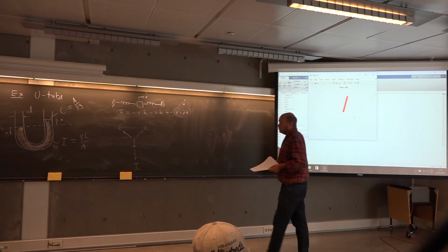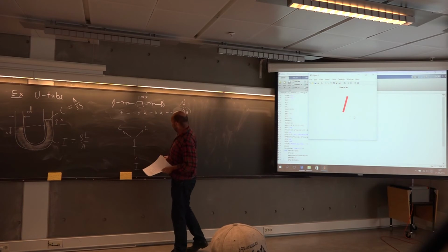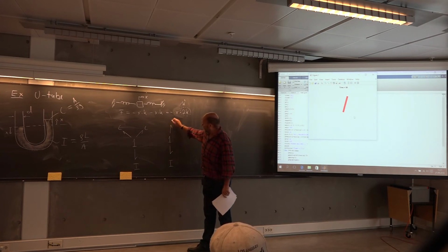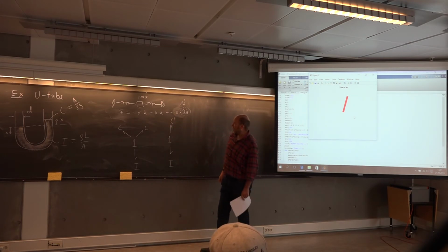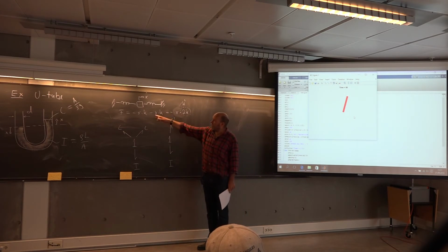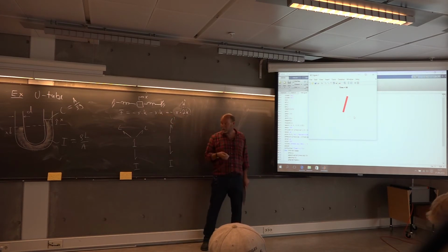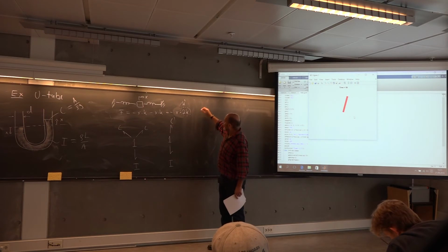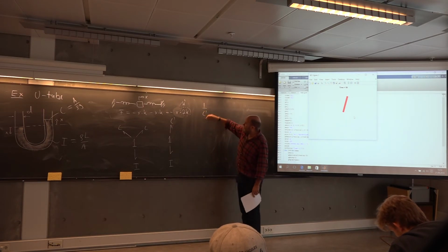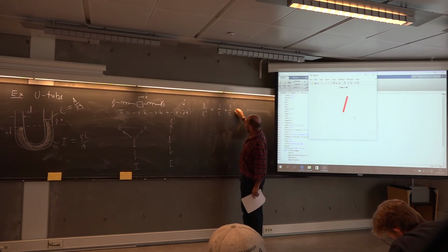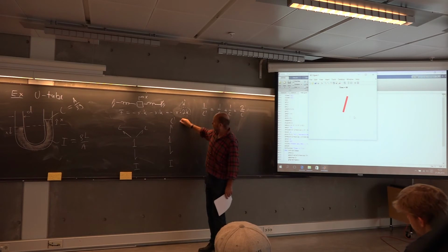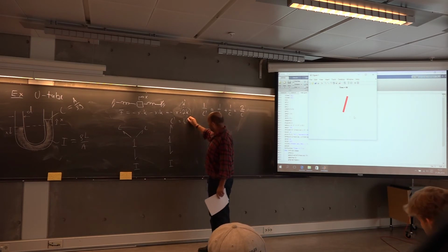So we do the same here. These two can be joined. So I will have the following bond graph: inertance, and just a C equivalent. And how to find it? Well, here you can add the spring stiffnesses directly, but remember the compliance, that's 1 over the spring stiffness. So we have the following equation: 1 over the equivalent compliance equals 1 over c plus 1 over c, which is 2 over c. So it will actually be 1/2 of c.